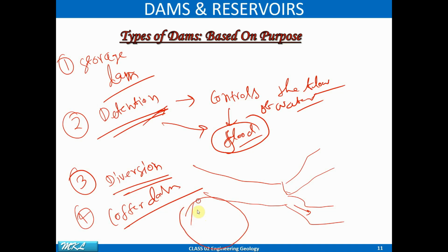So this area has been excluded. What you will do is encircle an area with some non-leaking material. Okay, you will put up a temporary dam and build the pillars or the support pillars or whatever you say. वो सब build करोगे, उसके लिए जो dam बनाओगे उसको coffer dam बोलते हैं. Okay.